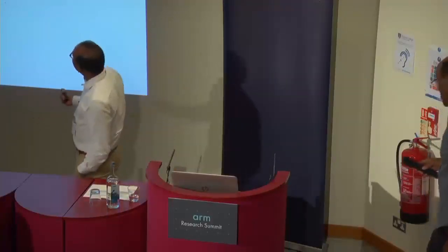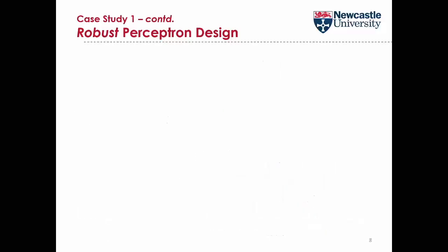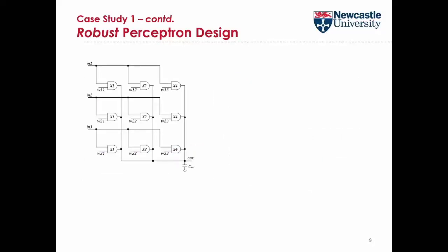What kind of technology was it? Okay, so let me just show you the circuit. I basically skipped the technology stuff. So here, we are using the 65 nanometer technology, but the width was increased, doubled over here, and it was quadrupled over here. So the idea was to also compute in the 2's domain, analogously, if you like. It's sort of digital in terms of standard cells, but we do analog things basically. And if you go to the analog end, they don't work with sub-threshold.